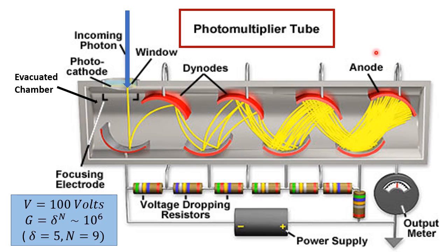So eventually you have the anode, which collects the whole current, and that is what is basically measured in the output. So imagine that the multiplication factor for each electron was 5, let's say, and for every one of them this happens n times. So this is delta to the power of n. It becomes the overall multiplication factor after it has gone through these n dynodes.